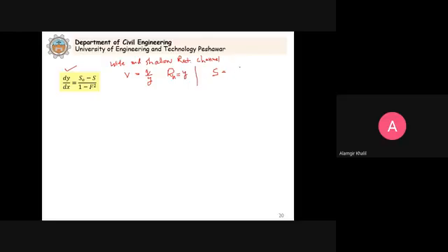This S will be equal to (n q divided by 1.486 Y^(5/3)) whole squared, with 1.486 being Manning's formula constant in BG units. And similarly, we can also write down S naught in this fashion.